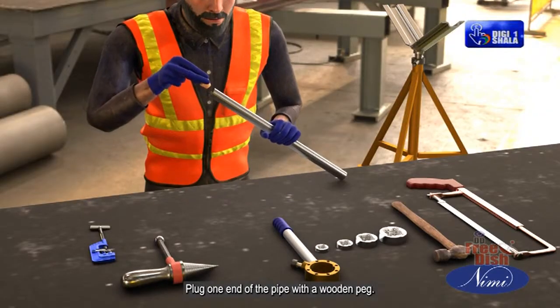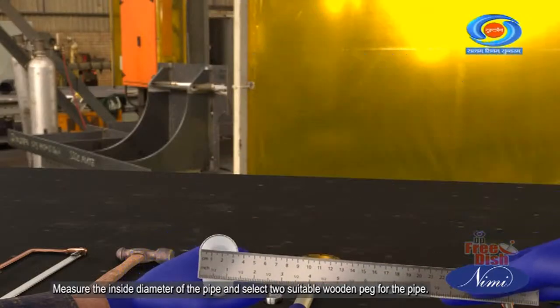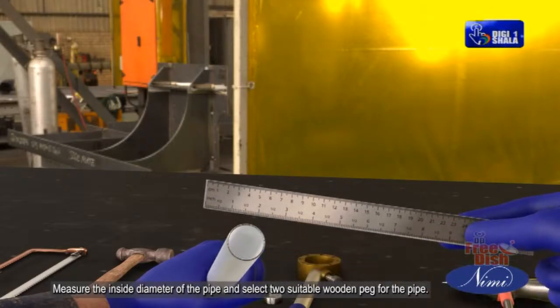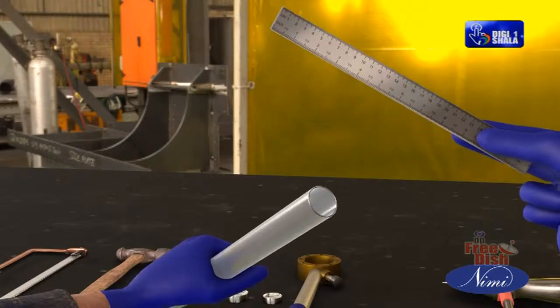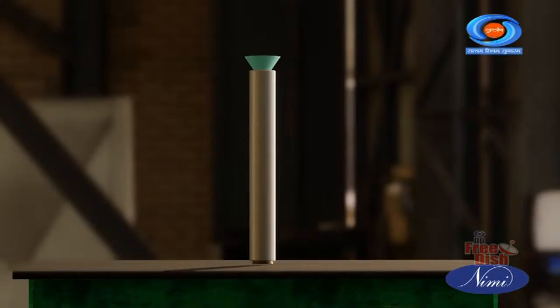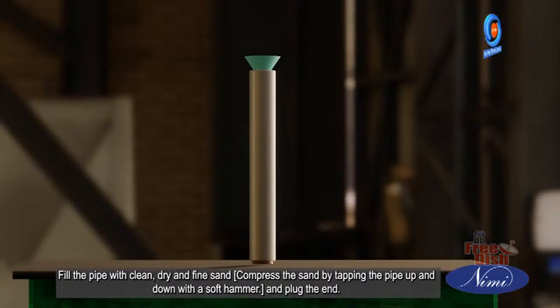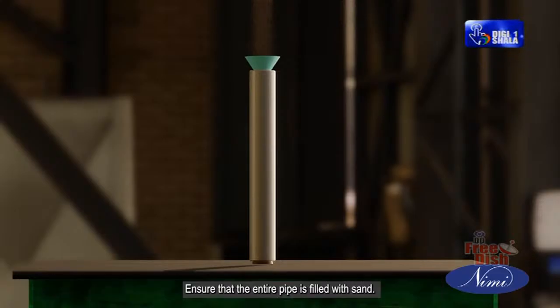Plug one end of the pipe with a wooden peg. Measure the inside diameter of the pipe and select two suitable wooden pegs for the pipe. Fill the pipe with clean, dry and fine sand. Compress the sand by tapping the pipe up and down with a soft hammer and plug the end. Ensure that the entire pipe is filled with sand.